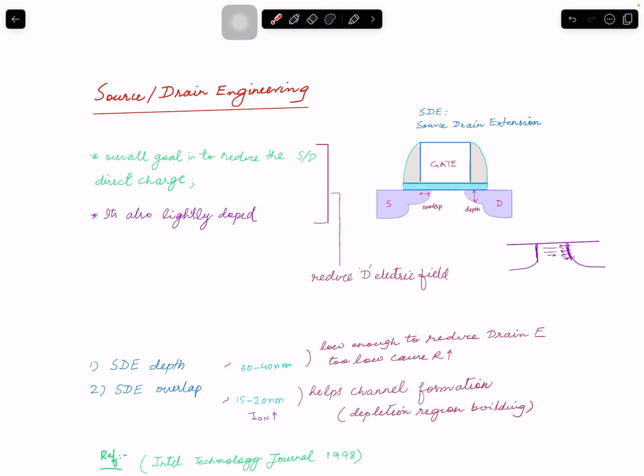This overlap helps because it creates a depletion region underneath the gate. Okay. Keep in mind that this is N, this area is P. So when it's connected in a way, this whole junction is reverse biased. So moving this underneath helps in some way to create this depletion region. Remember how this channel conducts? Initially, when you apply a positive voltage here, it pushes all the holes away. So in this region, we create a depletion region. I mean, it doesn't have anything. And then a little bit more voltage applied here, all the electrons come from here and drag from here, and they create an inversion here.